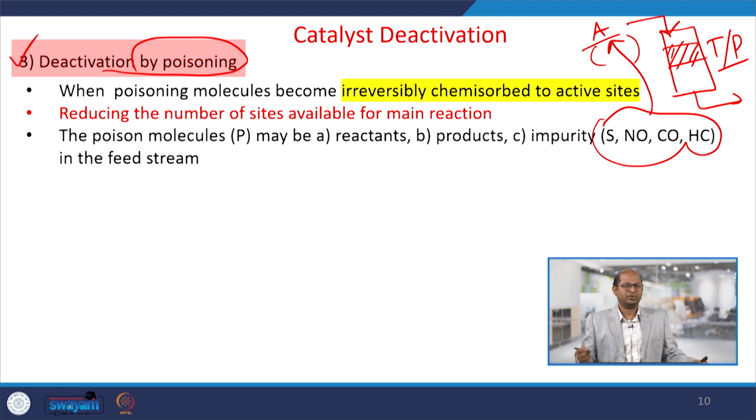Okay. So, 100% pure compound is sometimes not available for industrial operation or industrial study. Some impurity may be there, and sometimes it is not possible to separate out all of it. So, some fractions may be present and pass with the feed stream or reactant streams coming inside the reactors, and may be deposited over the surface of the active sites of the catalyst. As a result, the catalyst active sites would be blocked by those poison molecules. Then that active site would not take part in the reactions, therefore the overall performance of the catalyst will deactivate. These molecules are sometimes called poisons.